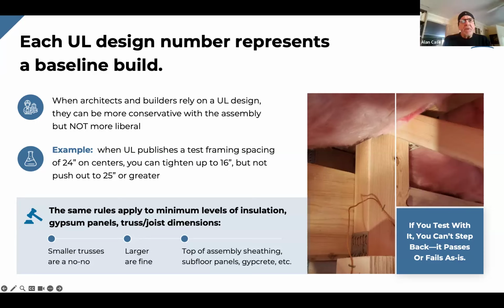Well, we wanted the least restrictive build you can have, and so the minimum truss depth was 12 inches. So we built with that. We set those at 24 inches on center. Then we added the HushFrame connectors on a 24 by 48 inch pattern. So the furring strips that we used underneath were 24 inches apart, and the HushFrame was scattered every 48 inches along every other truss.